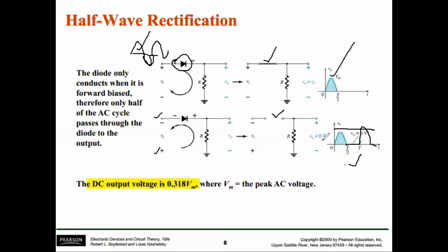Later on, we can make other configurations that we have discussed in our class. We can use here a capacitor as a filter to remove the ripples. So it will move and then go here, it will move and then go here, and at the end, by using complete filtering, this will be like this waveform, and this is called a DC waveform.